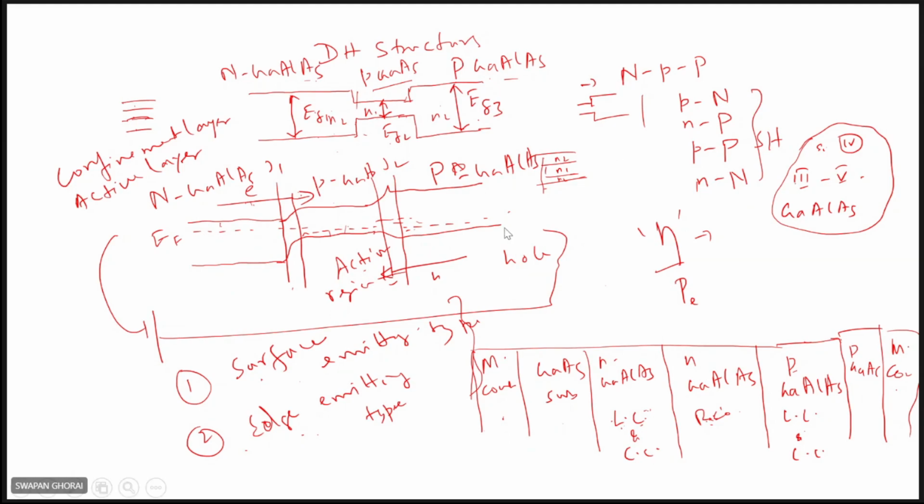High power output is related to power emitted per unit solid angle per unit area, that is, high brightness. We will see what factors can be used to increase the power output of LED. Another factor is response speed, the delay between the application of the pulse and the onset of radiation. That should also be minimum.